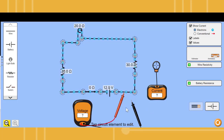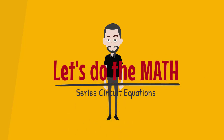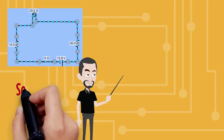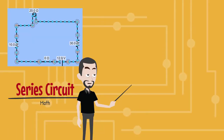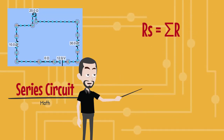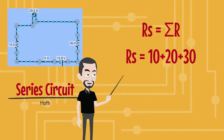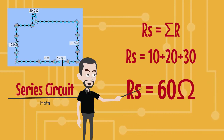And how can we use math to make those predictions so we know what we should get before it's ever built? So after seeing the simulation and realizing what the circuit's supposed to do, we need to explore the math on how it actually works. In the upper corner, we have a schematic diagram from our simulation. To figure out the equivalent series resistance, we have to add up all of the individual resistors in that series. So we're going to add the 10, 20, and 30 ohm resistors, meaning this circuit works as if it had a total resistance of 60 ohms.